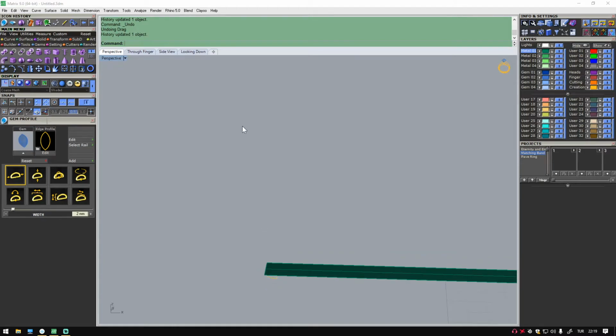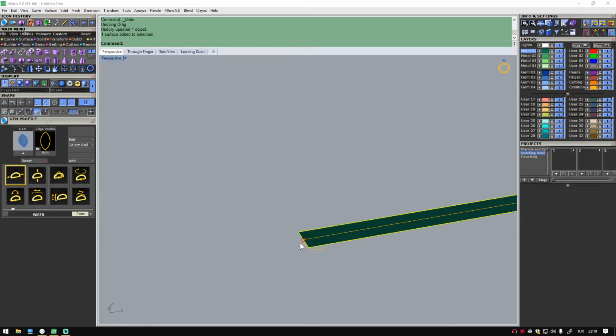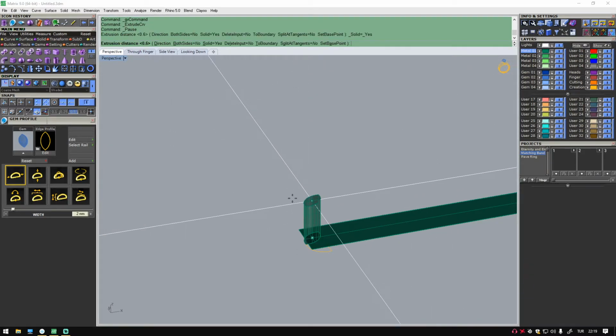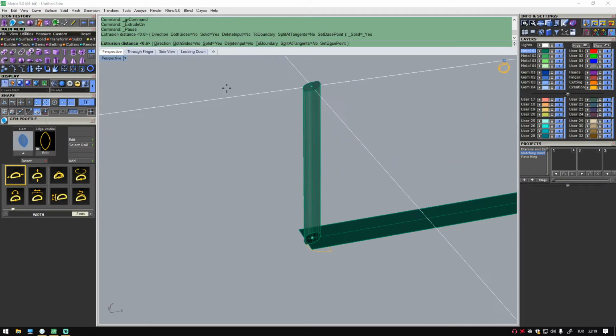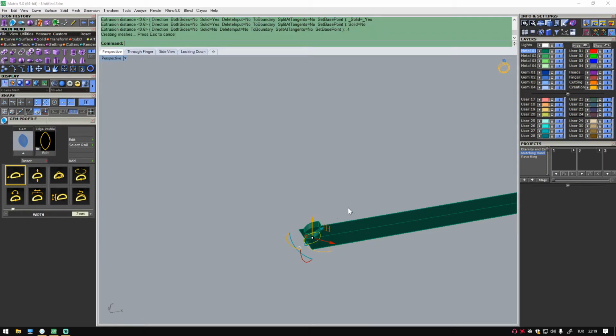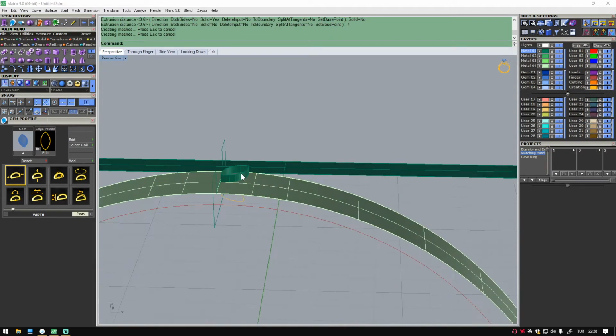Okay. Now I want to extrude this curve, the first one that we designed, that we drew here. I will go to solid, extrude curve straight, upwards. And I want it to be a solid no because I want it hollow inside. You will see why. And I will type in 0.4. Yep. You can see it's already coming here in shape.